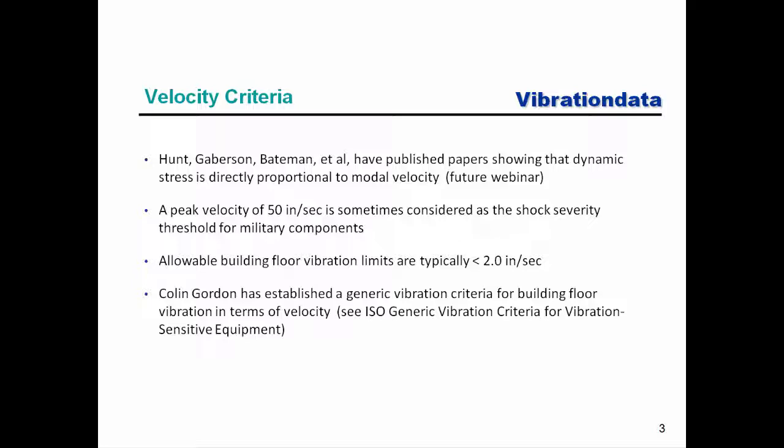So if a military component will be subjected to a shock that has a pseudo velocity of less than 50 inches per second, then shock testing may not be required or may be optional. But if that same component is to be subjected to a shock with a pseudo velocity of 50 inches per second or higher, then shock testing would be required. We'll cover more about that later on when we get into our shock units.